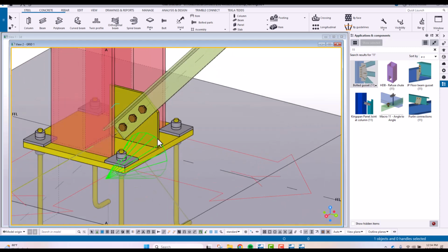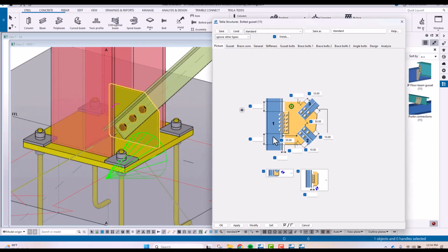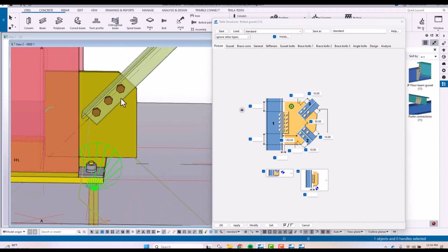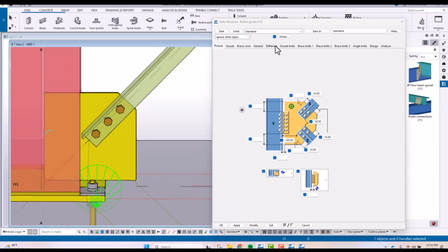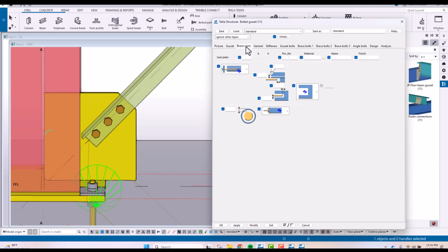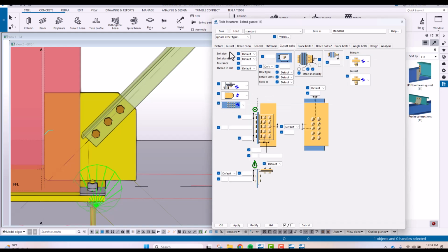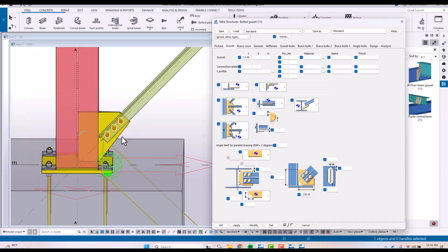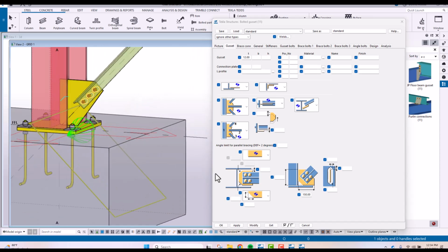Because this one is too near, you can change this one to maybe 150, modify, something like this. Yeah, 150. And then here you can change the gasket to 150 as well. And then apply.